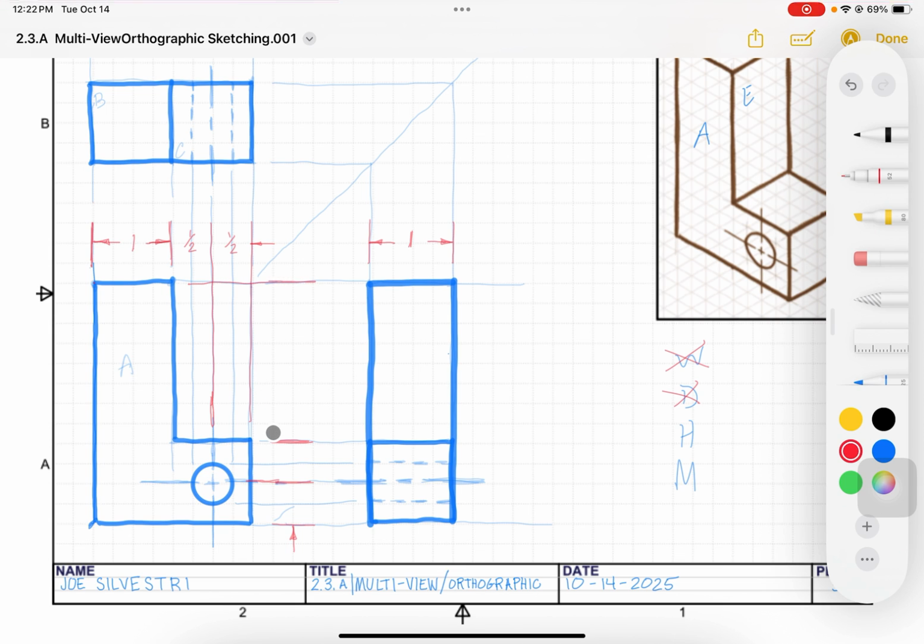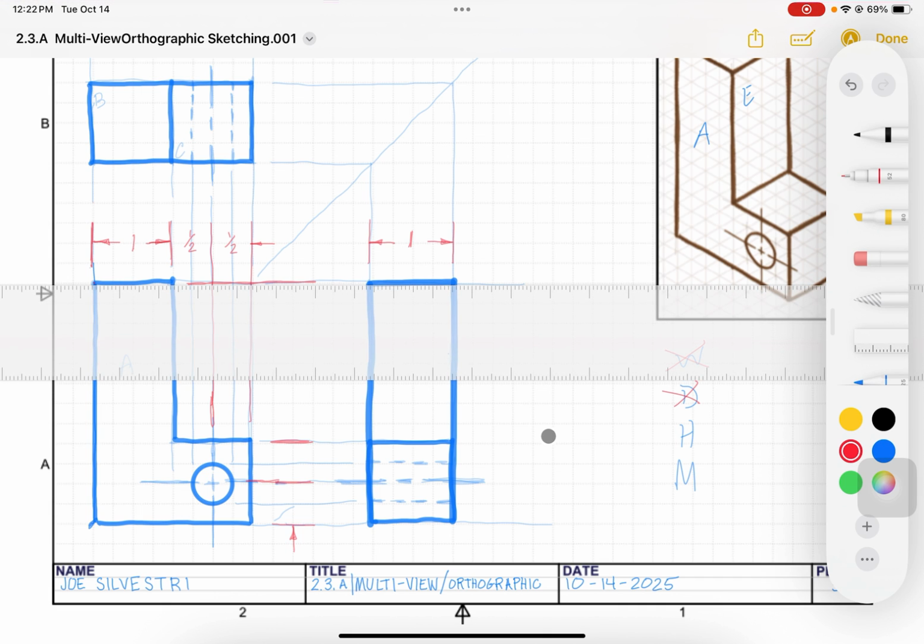and draw this out. Now again, do you delineate these extension lines and dimension lines? Yeah, a little bit with your 6H pencil. That's fine. Okay. But again, we're not going to use our 2H pencil. We're not going to make them super dark and thick. We just want them to stand out from the construction and projection lines. Okay, so now back to our dimension lines.